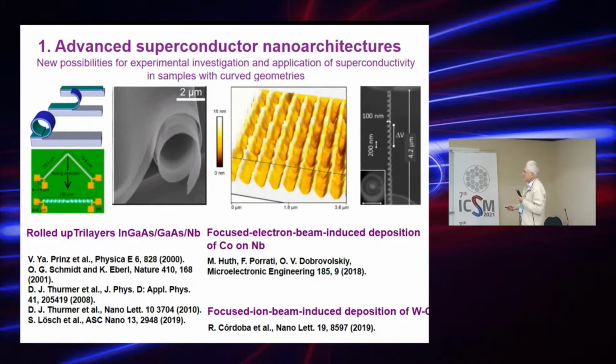Imagine a double layer of two crystalline materials which are super thin, maybe 100 nanometers. And they are put on a substrate, but not directly. There is another third layer, which is white. You can see this white layer. And this is the sacrificial layer. Why is it sacrificial? If you start etching it off from the side,